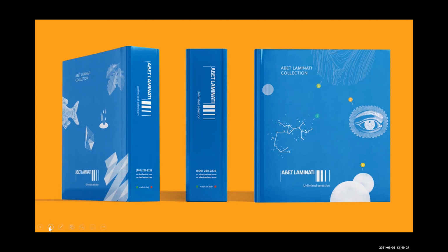Grayson? And, yes. Before you go, we did have a question that was in the chat box. It says, some of the projects I work on are state funded and they require plywood substrates for countertops. What other specification besides grade A plywood differ from a spec for MDF or particle board? Okay, so if I understand this correctly, honestly, the only substrate we would say is acceptable would be that grade A plywood, marine grade plywood for that type of application.